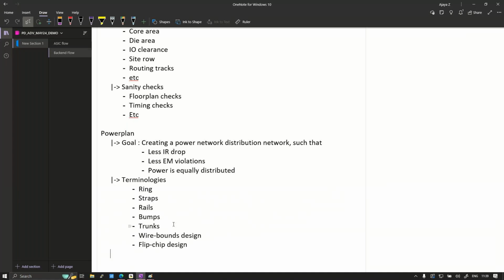Okay. So now in this particular flow, power plan, again we will check for basic checks: how our particular power structure has been formed, how we can rectify it if it is not getting properly formed, or how to create the missing nets. Everything we will be performing from the labs perspective. Again, after this power plan, the compulsory task is log file observation.